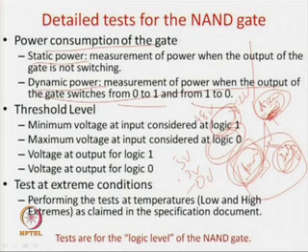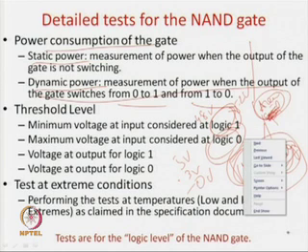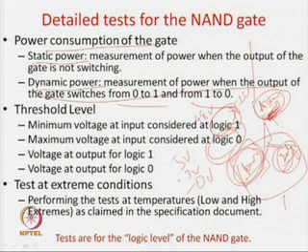Now, for all the tests I have done for zeros and ones, I have to apply this to all the inputs. In the case of the NAND gate in table 1, as we have already seen, we apply 0 0, 0 1, 1 0 and 1 1, and then we get the answers 1 1 1, and after this pattern we get the answer 0. Now, for each you have to measure the voltage.